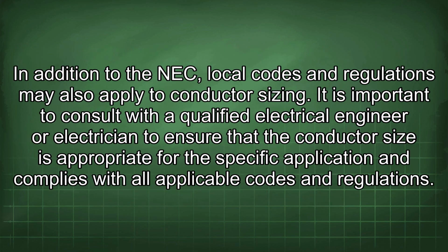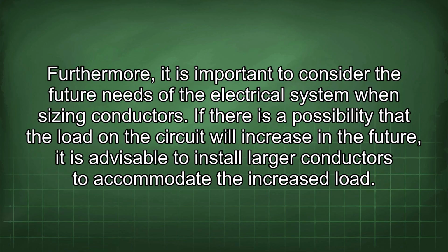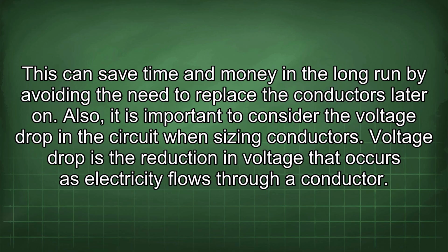In addition to the NEC, local codes and regulations may also apply to conductor sizing. It is important to consult with a qualified electrical engineer or electrician to ensure that the conductor size is appropriate for the specific application and complies with all applicable codes and regulations. Furthermore, it is important to consider the future needs of the electrical system when sizing conductors. If there is a possibility that the load on the circuit will increase in the future, it is advisable to install larger conductors to accommodate the increased load. This can save time and money in the long run by avoiding the need to replace the conductors later on.